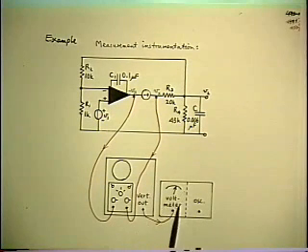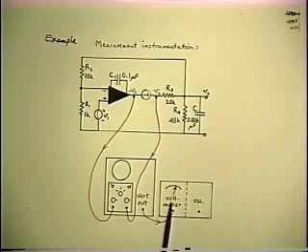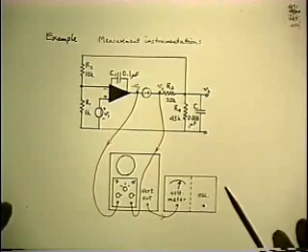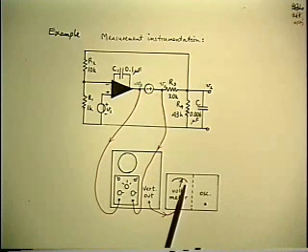In fact, the HP instrument that I use has a 90 dB scale on it. I think I mentioned that one before in talking about observing the nulls when we do null double injection. Anyway, that's a pretty basic instrument and not that expensive. So it enables you to measure very small signals. Okay, the next thing we want to do is automate a little bit how we measure the magnitude and the phase, because it only measures magnitude.